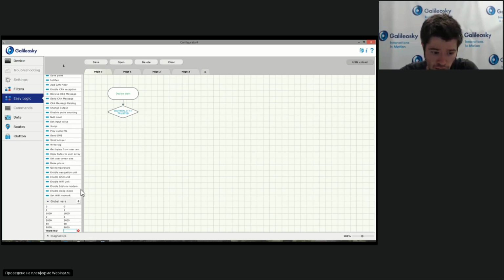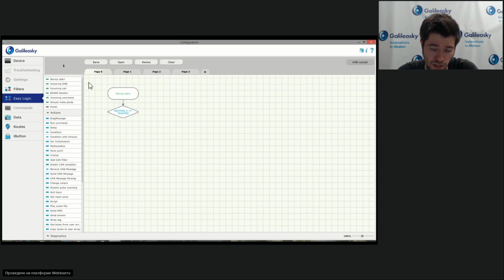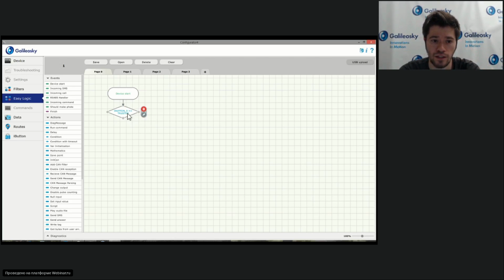If it's one specific card, then you can simply enter the ID here, and the iButton 0 will be checking the trusted key, which is 823748424. If you have a whole list, then we check a bit in the status field. I will not cover this now because that's a bit complicated, so you can look it up in the Easy Logic Basic course or ask our tech support. But that's simply checking the 4th bit of the status field.